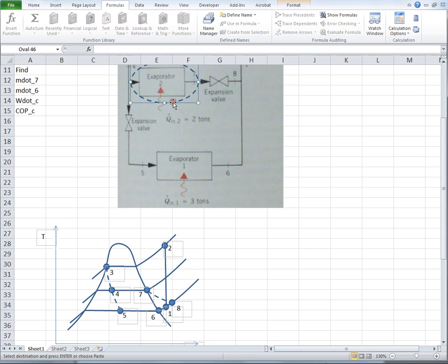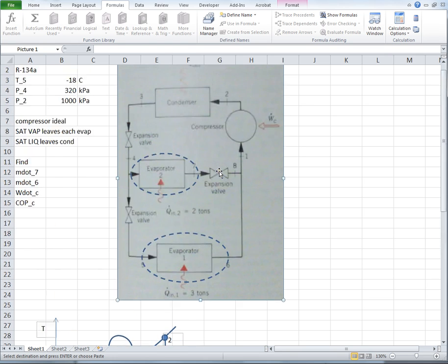And how did we do that? Of course, we just put a control volume on this one, and it looked like that. So anything that crosses the control volume boundary comes into our first law equation. We've got the heat added, the m dot H5 in, and the m dot 6 H6 out. And implicitly we've used the fact that m dot 5 equals m dot 6 because it's just steady flow through there.